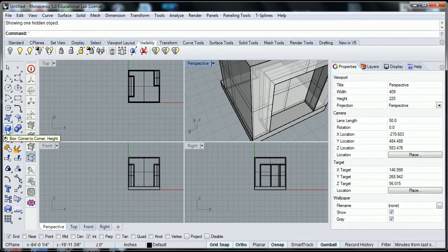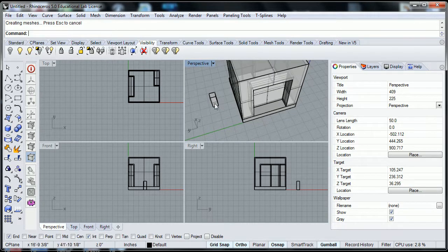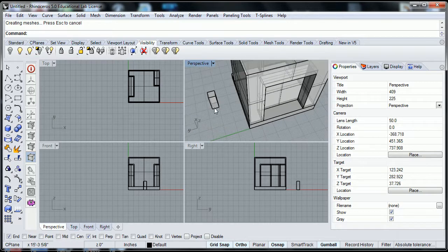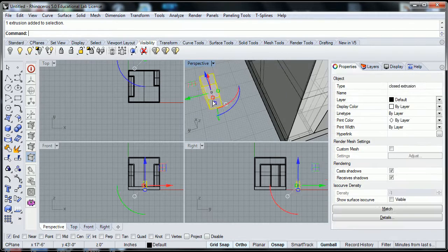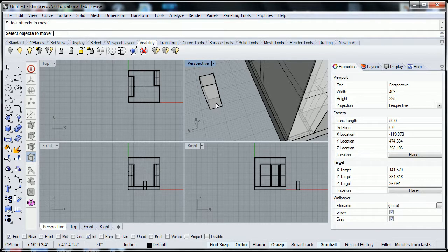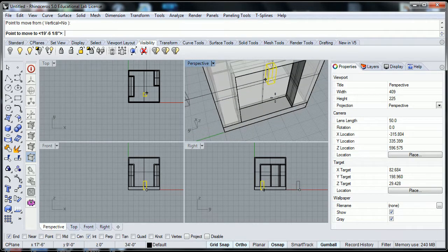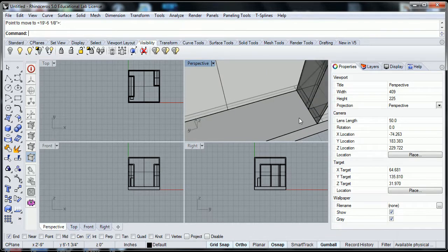So in order to do that, a door is what, 3 foot wide by 7 foot or 8 foot high. So to make my life easy, I'm going to draw a 3 foot comma 3 foot box, and then make that 8 foot high. So it doesn't matter which side I use, I know I have a 3 foot by 3 foot box. If I take this thing, I could move it to the inside corner right there.